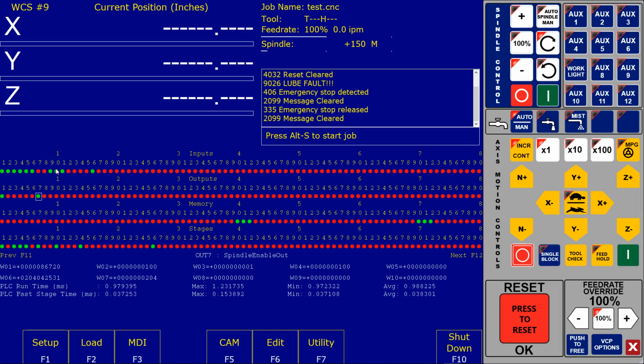Now it could be that perhaps the relay isn't in fact turning on, or maybe there's a fuse associated with it that got broken or blown. Maybe there's a broken wire in the system, or if it's controlling a solenoid, perhaps the solenoid is going bad.